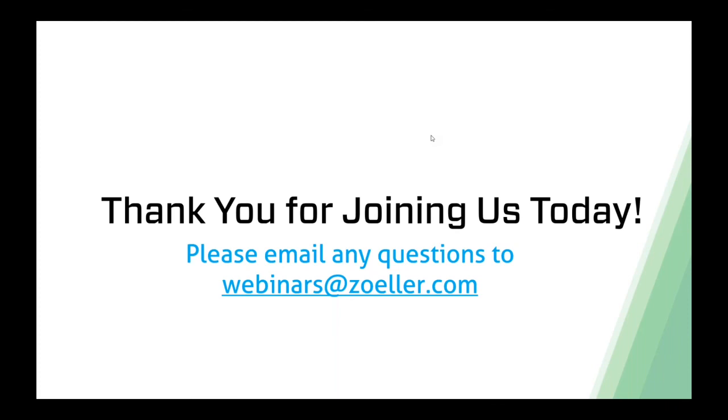There was a question about different kinds of 90s. If you have a short turn 90 versus a long sweep 90, are there differences in friction loss? This actually brings up a point that I should have made earlier in the presentation: the methods of pump sizing that we talked about here are all estimations. It can be easy to get caught up in the decimal points. We see a friction loss factor of 2.64, and it seems very accurate. But all of these are just methods for estimating what friction loss you're going to see and what you're going to get out of your application. So is there going to be a different friction loss factor for a sweep versus a tight 90? Yeah, there would be different values.